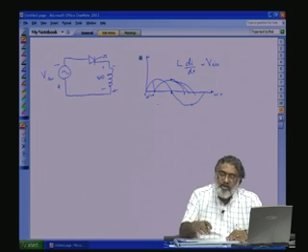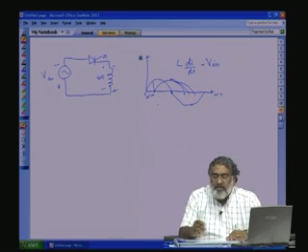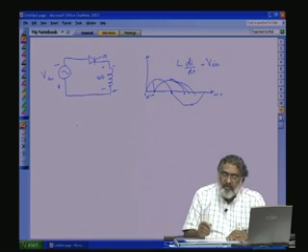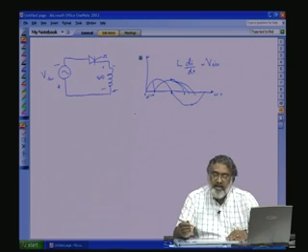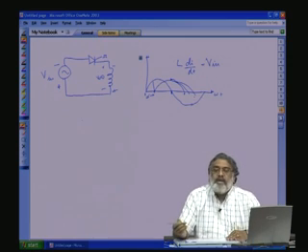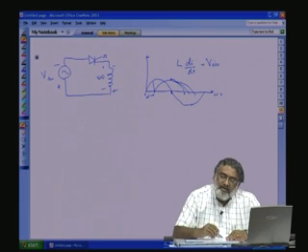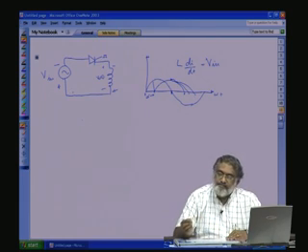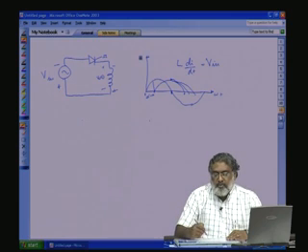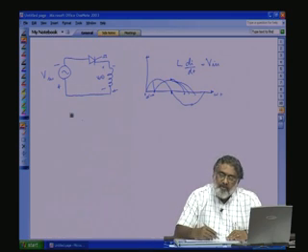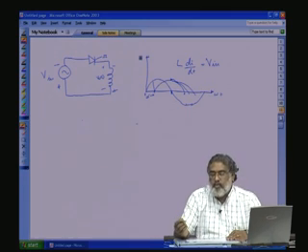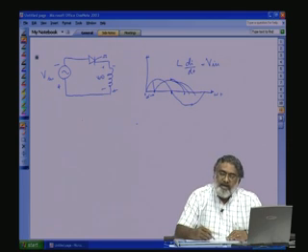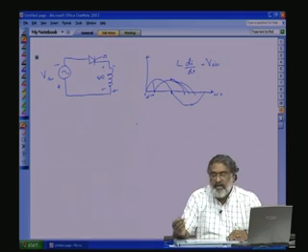So we don't know what is the output ripple coming across the inductance. So the previous equation for the resistive load, the output with respect to firing angle alpha, equal to Em by 2 pi into (1 plus cos alpha), is no more valid here, because there is a negative conduction, that is, when the input voltage has gone negative. So for this equation, that is the output DC value, to be valid here also, this negative side we have to remove. That means there should not be a conduction, or there should not be a negative ripple coming across the inductance.